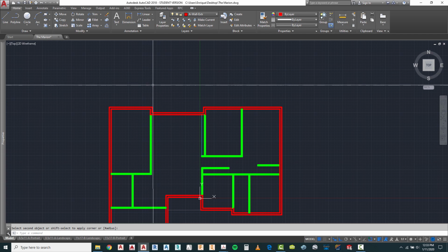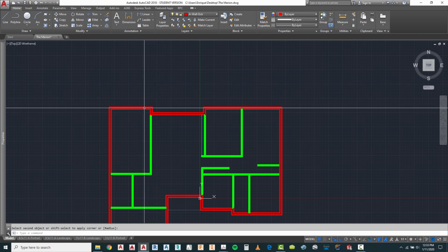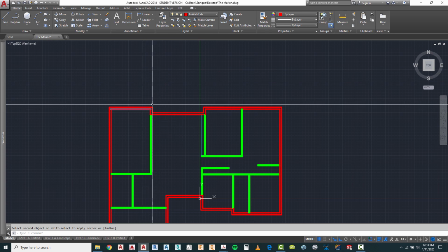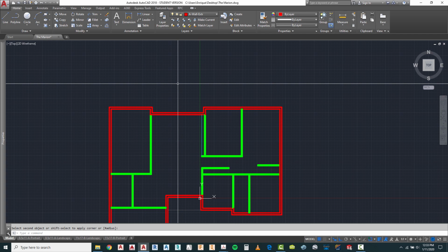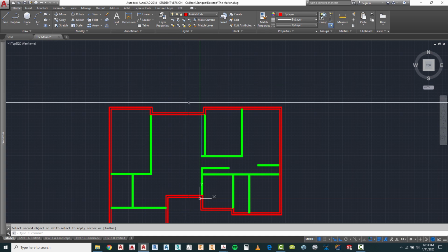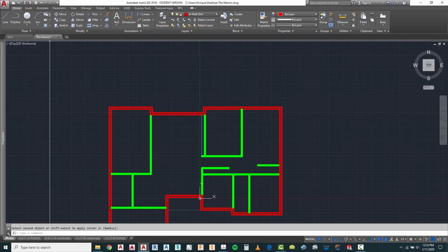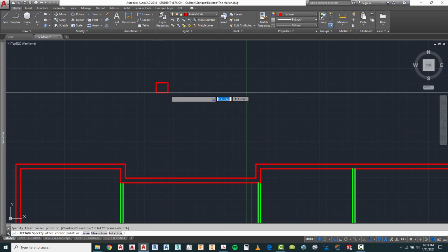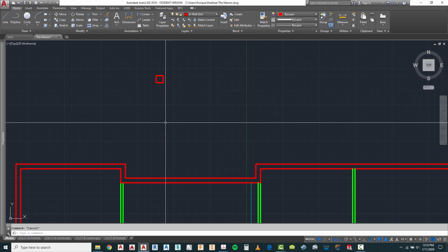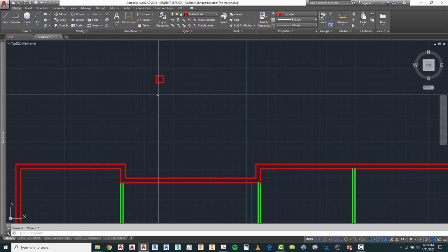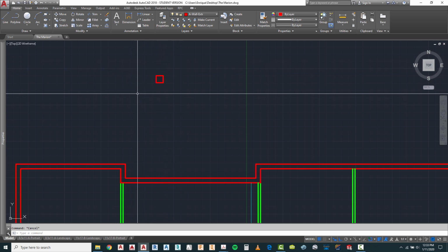The porch columns are actually set in the same material as your exterior walls. They're composed of concrete block, but instead of being the standard 8 by 8 by 16, they're going to be 12 by 12. So we can either go to the rectangle command and type 12 by 12, or we can use line work and just work your way around onto that.